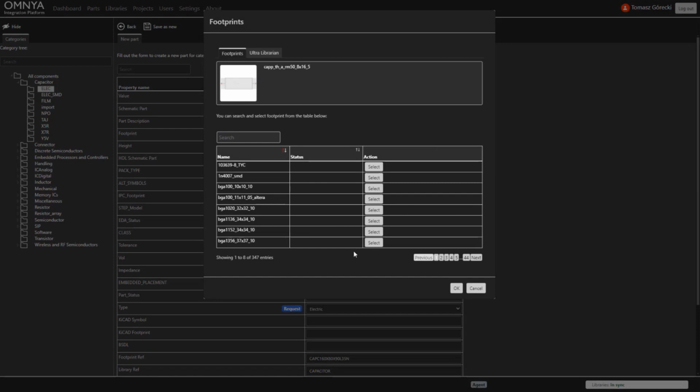So this is the list I can choose from, whatever I want, and I am sure this is something that was already verified by somebody else probably, and I am very safe when I decide to use anything from this list. So let me search for some capacitors. If I click here, select, you will see the change here. So a very easy way.